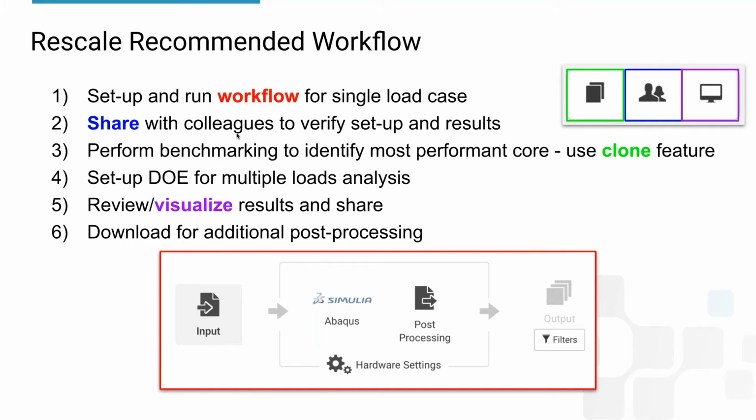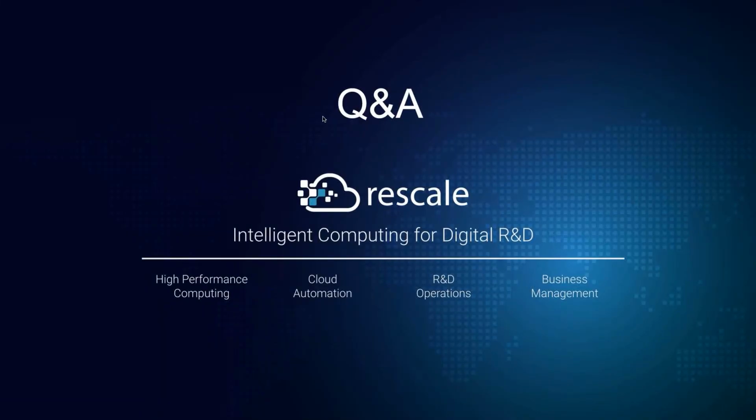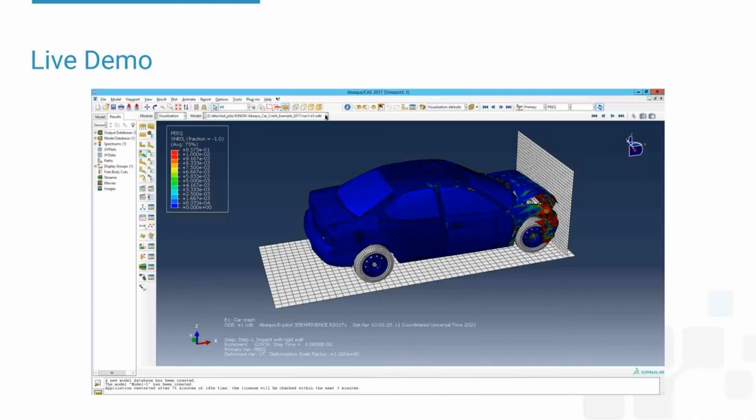The structure of the actual parametric analysis will look something like this down below. So we'll upload input files, we'll specify some variables that will control the sweep, and then we'll add some additional post-processing steps so that we can quickly extract the KPIs that we're interested in without having to download the full result set and interrogate it that way.